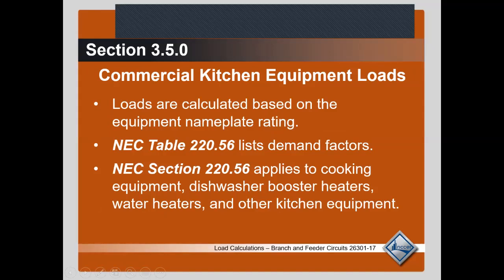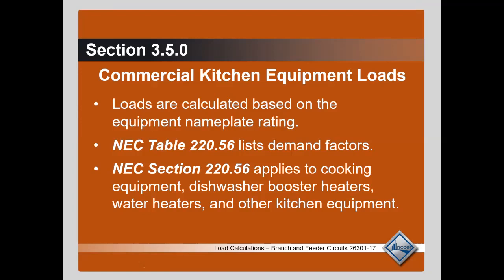Commercial kitchen equipment loads. Loads are calculated based on the equipment nameplate rating. 220.56 lists your demand factors. 220.56 applies to cooking equipment, dishwashers, booster heaters, water heaters, and other kitchen equipment.